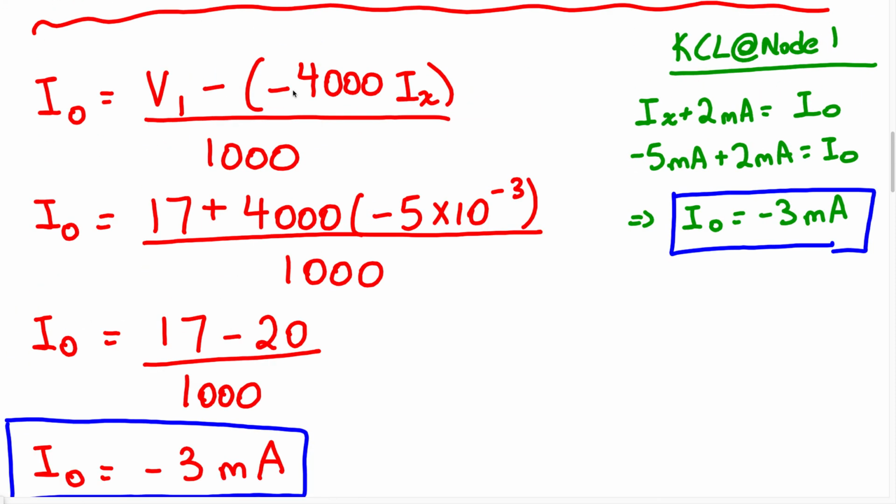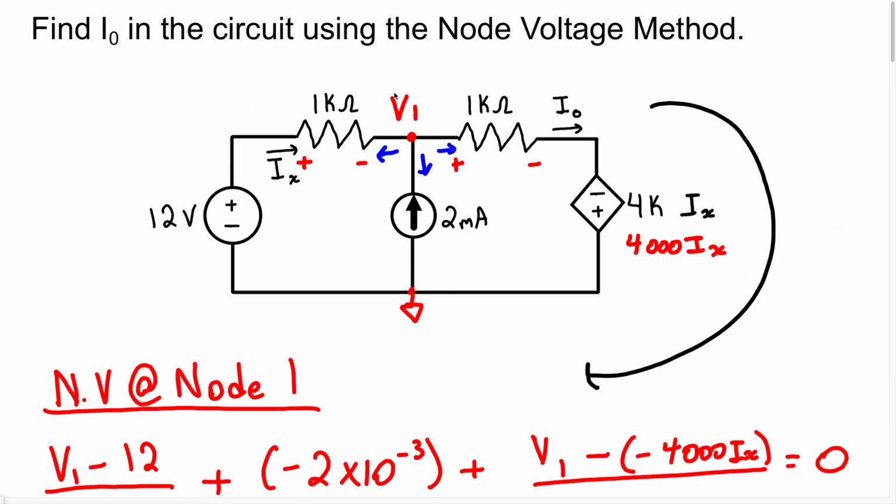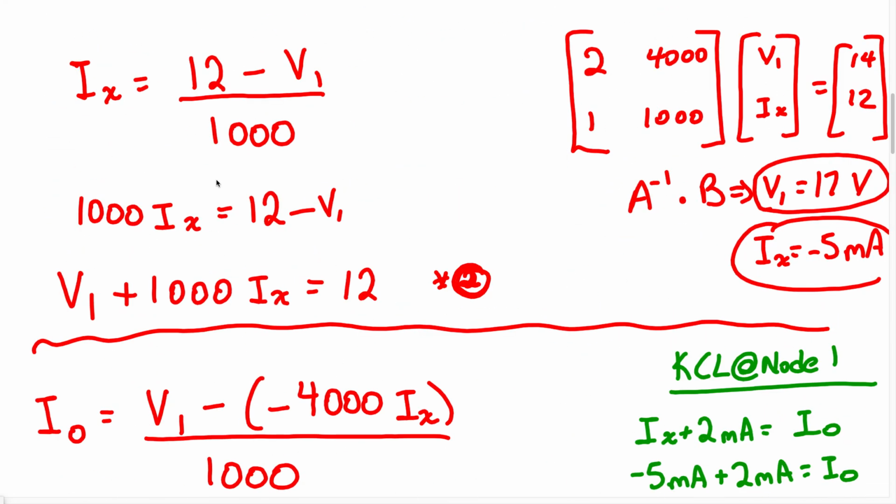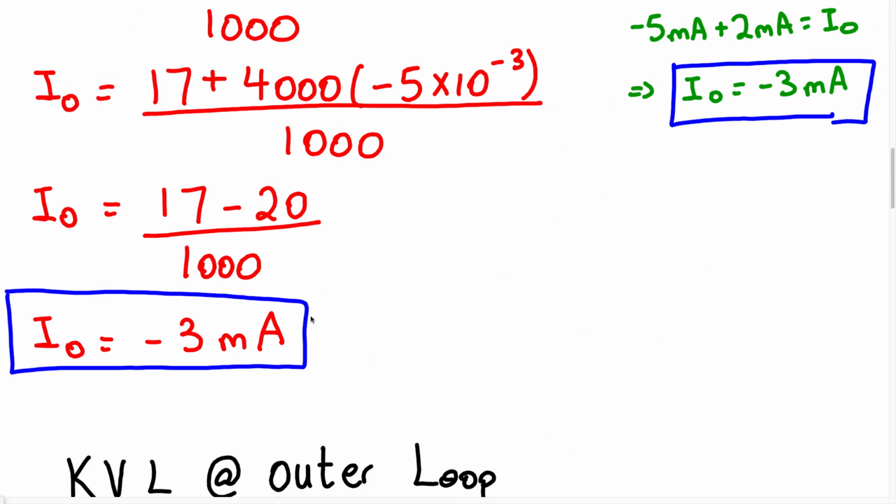So we were able to use Ohm's law, right? And we were able to find the voltage across that resistor because we know that node 1 would have had a higher potential than this voltage source, so we subtracted to find the voltage across this resistor, and we knew the value of this resistor, so we just divided by 1000. We calculated the current flowing through that branch.